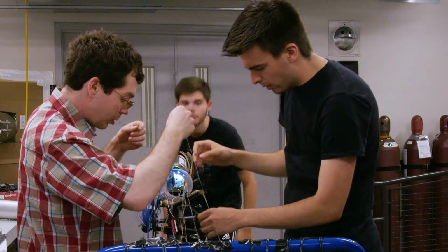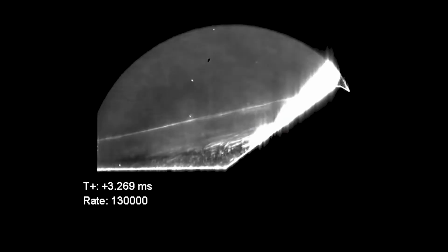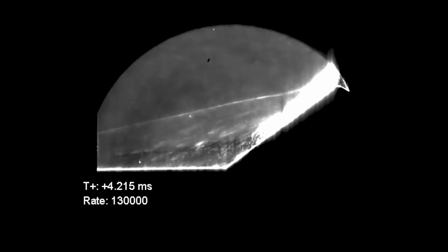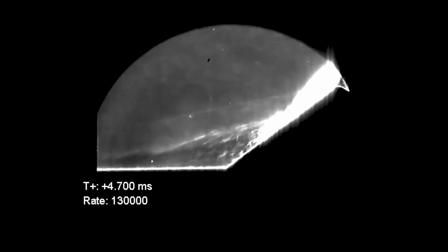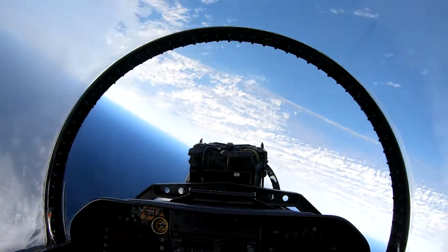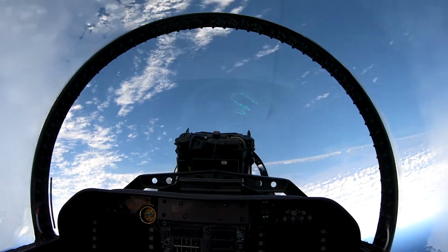and the surface. So we can actually study the pressure gradients and understand what's happening during this flow, both the starting of the flow and the ending of the flow, which are the transient periods, as well as the steady state. Basically, what we want to do is simulate and analyze flow at Mach 6 over these articles. What this could tell us is if you have some sort of hypersonic vehicle flying at that speed with the same geometry, you could basically simulate the interactions.